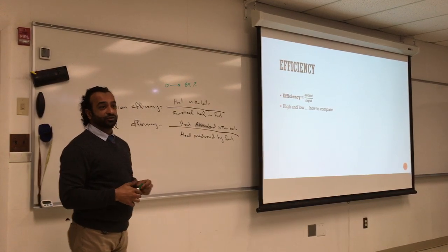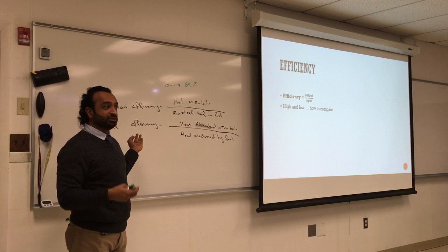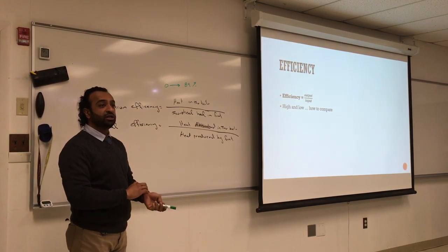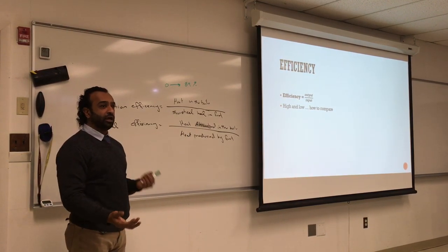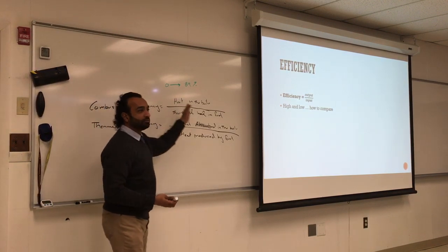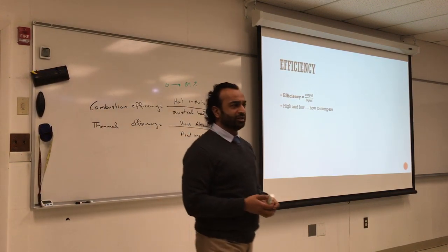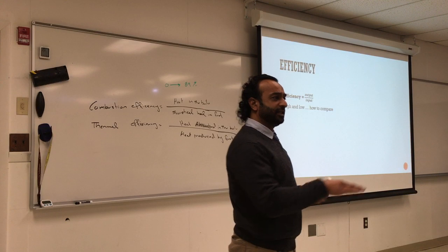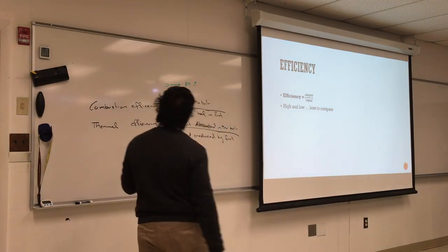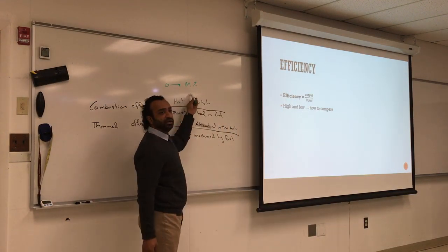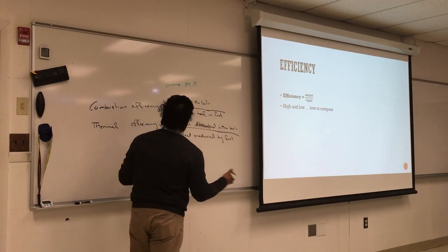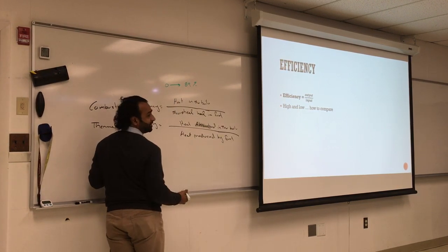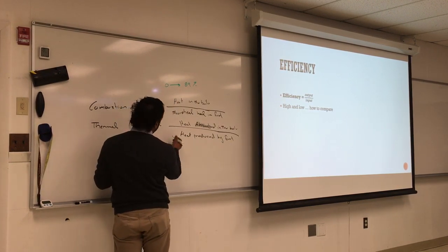Depending on how much you burn the fuel, it's 0 if you didn't burn much. You're going to have lower and lower efficiency, that's combustion. Depending on the air mixture and the heat, it goes up. When you first turn on the boiler, the combustion efficiency is probably low until it stabilizes. And in theory, it does not go more than maybe 89, 90 tops. It does not go to 97. That doesn't make sense at all.